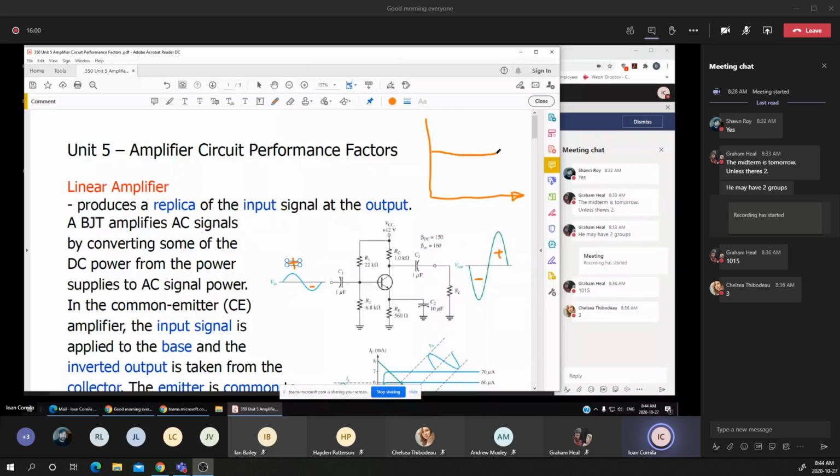If that's the DC voltage, I'm making the assumption that's the DC voltage that is created by the biasing of a transistor. Now we are applying an AC signal which is superimposed on a DC voltage. You notice that the DC voltage is above the x-axis, and if we are not placing the transistor in with the proper bias, some of these waveforms may be clipped.